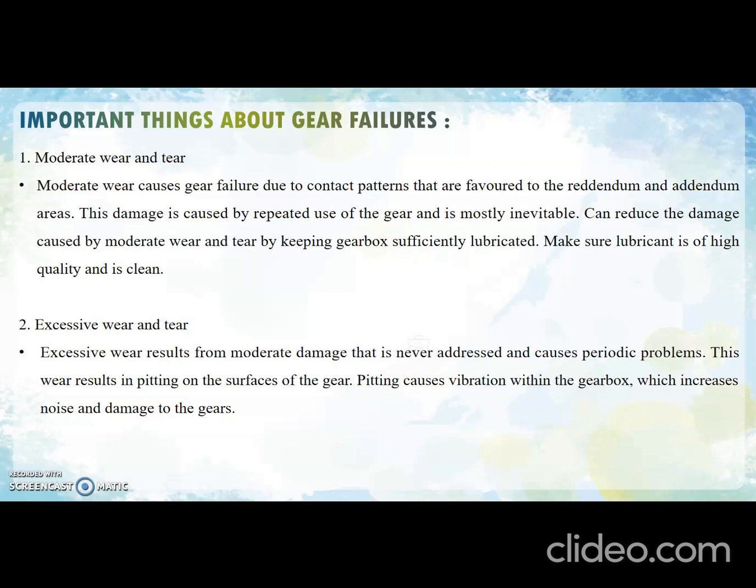Next is excessive wear and tear. Excessive wear results from moderate damage that is never addressed and causes periodic problems. This wear results in pitting on the surface of the gear. Pitting causes vibration within the gearbox, which increases noise and damages the gear.